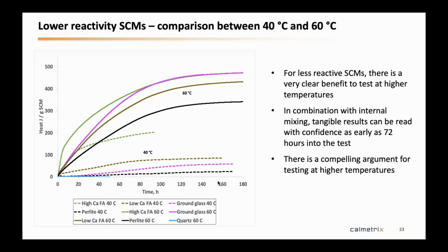But when we do our experiments and try to find new materials, we should probably not restrict ourselves to something as restrictive as the temperature here, because we see at 40 degrees, as you can see here, it doesn't tell you much on low reactivity materials. When you push that to 60, it starts getting more interesting. So it's good to experiment around, and actually it's good to do it at several temperatures. And why not do it at several temperatures and actually calculate an apparent activation energy and do some modeling and derive something? It opens the door to other things.